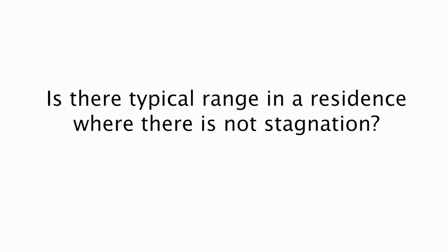Well, there is. Whatever that P0 value is, that's built into the calculator. It will calculate a value for this P0 depending on the number of fixtures you put in the calculator and what the probability of those fixtures are. And the calculator will find the P0. You would have to have a lot of fixtures. I mean, it would have to be a huge complex of multifamily dwellings for this to reduce to no stagnation. You're going to always have some range of stagnation in a residential dwelling.